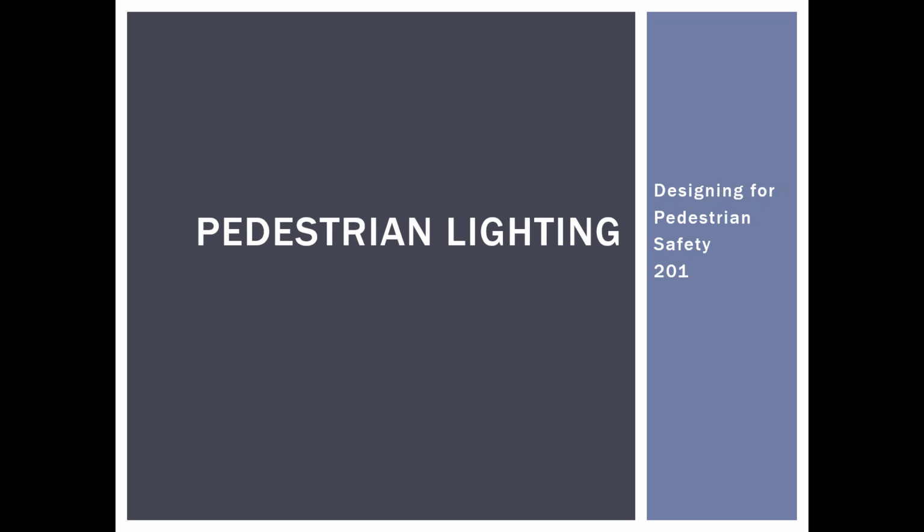Getting some more background, during the 1970s, I think some people will still remember the time of the Arab oil embargo, where many subdivision developments were done without mid-block street lighting to save on cost, to save on energy. And the standard practice was only to install single-sided lighting on many of the wide arterial streets. The entire time I was with Phoenix, there had been ongoing retrofit efforts to install the mid-block lighting that wasn't installed in the 70s and sometimes earlier, and along other facilities such as schools and churches that attract a lot of pedestrians during the hours of darkness.